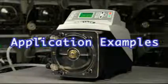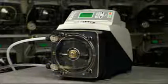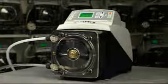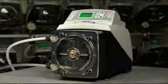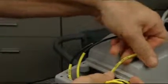Application examples. The A3 may be configured to start and stop output based on the status of a remote contact closure loop. The loop may be non-powered or powered by 6 to 30 volts DC. Connect the two contact closure loop wires to the lead wires labeled Input Remote located in the junction box.